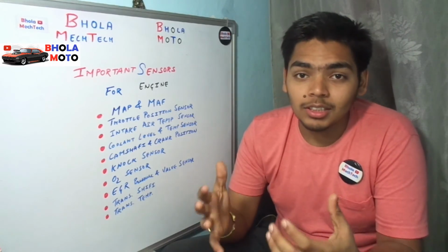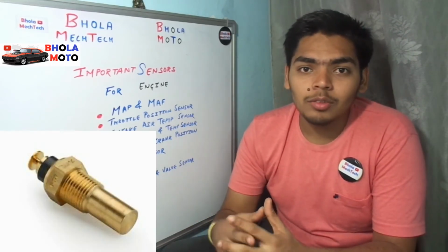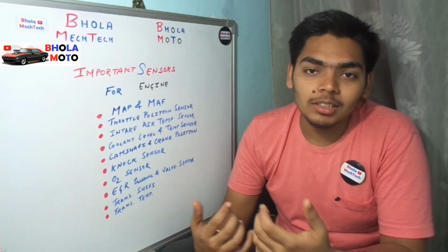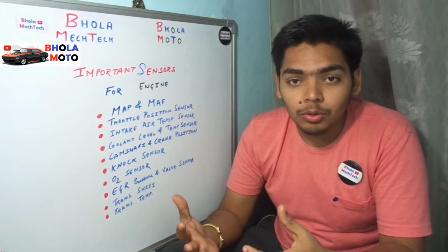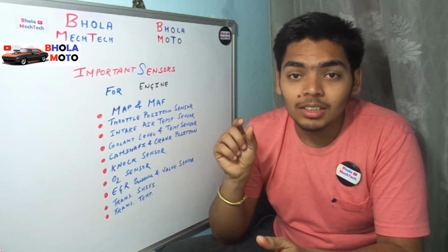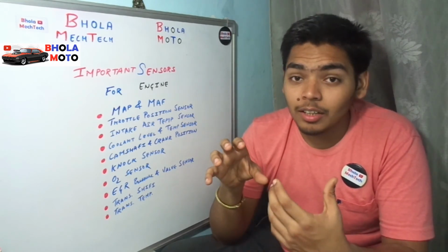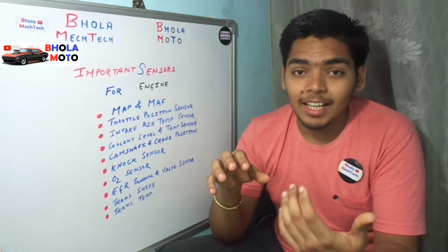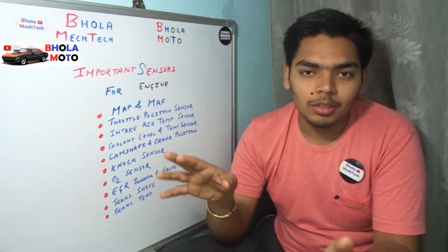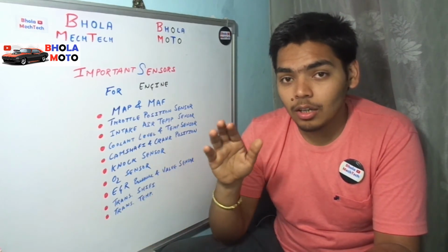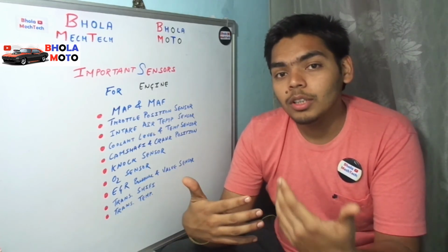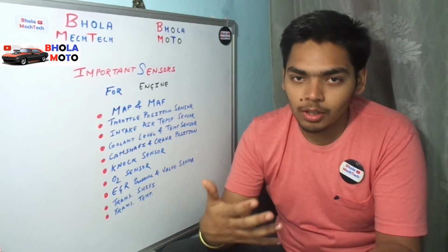The transmission temperature sensor is also a very important sensor, because whenever there is transmission, there is some meshing of the gears, and when there is meshing, there is some heat generation. So the heat is generated inside the transmission system. So that's why there is a temperature sensor which senses the temperature inside the transmission system, and if the temperature reaches more than a certain limit, it will give you a caution, so that you can give rest to the transmission system, and whenever it reaches the normal temperature, you can again drive your car. So as to avoid hazardous things happening to your transmission system.